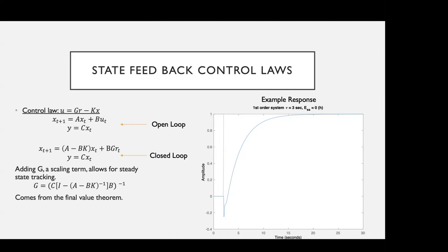But the question is how do you estimate performance? Depending on your filter, you're going to overshoot, you're going to overdamp, you're going to do other different things. How do you plug noise into simulations of this type? How do you actually evaluate how well your loop is going to do without actually doing it? In pole placement, there's some theory where you're placing poles in the complex plane.